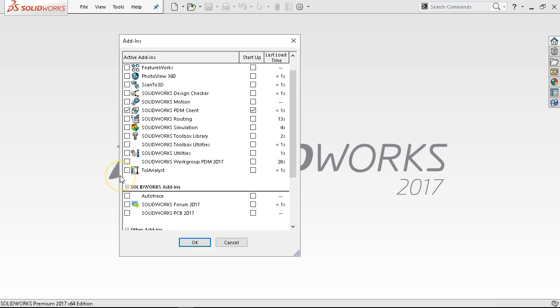Tolerance analysis is in conjunction with DIM Expert and, in net effect, with that model-based definitions. Once we've set up the conditions and the tolerances within DIM Expert and those go over to the assembly, we can generate reports on stack up of tolerances. What are the min-max conditions? What is the worst case scenario for our systems?